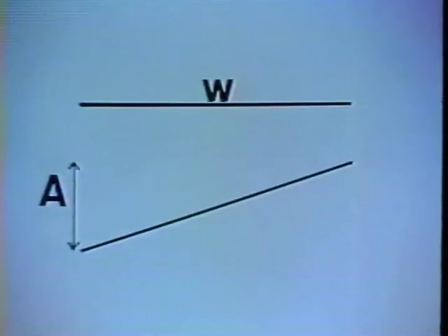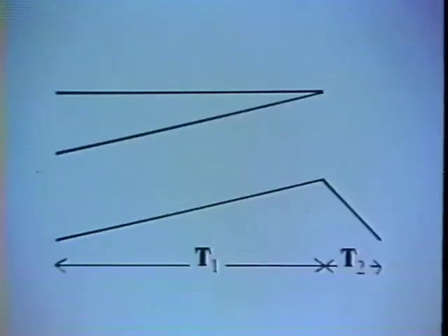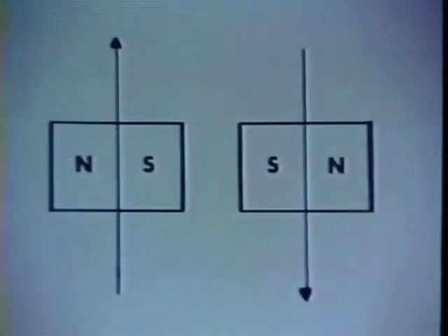The magnitude of the current will determine how wide the deflection is. The speed of the deflection is determined by how long it takes the current to rise or fall to its maximum and minimum levels. This is how the retrace is made much faster than the visible active left-to-right scan. The vertical movement is produced in exactly the same way. Another set of coils are used, and these are fed a signal from the vertical oscillator. This produces slow downward movement followed by a fast vertical retrace.